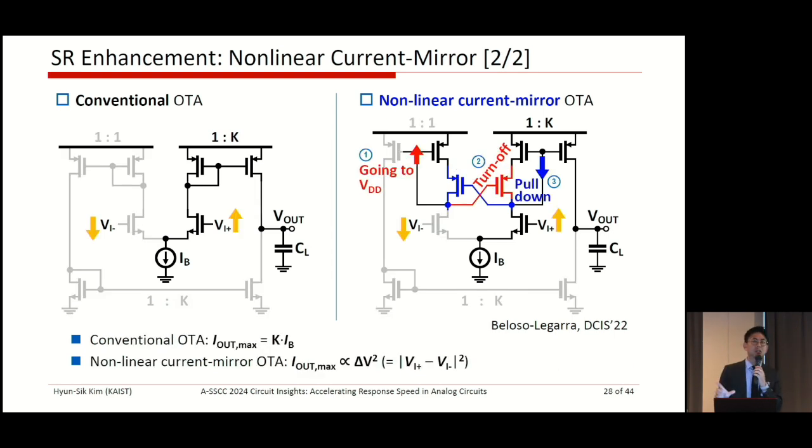when a large signal voltage is applied, the left-side differential pair turns off, so there is no current. Therefore, the gate voltage is pulled up to VDD. Therefore, the PMOS cross-coupled cascode transistor will be fully turned off. So this path is closed and this path is open, and this loop cannot work as a diode connection.